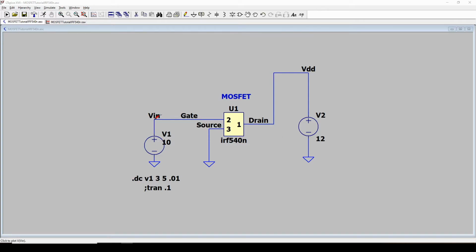Ideally, I would like to take the V in and vary it across a range. We said it's maybe 2 to 4 volts to turn this on, so I'd like to have the V in automatically go from 0 to, say, 5 volts, and just watch the current flowing from drain to source to see what effect that actually has in the real world.